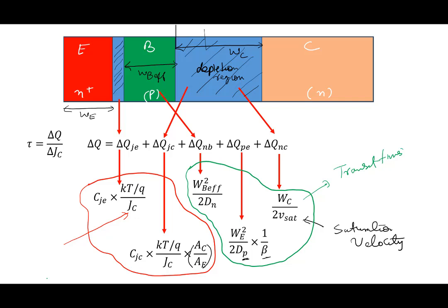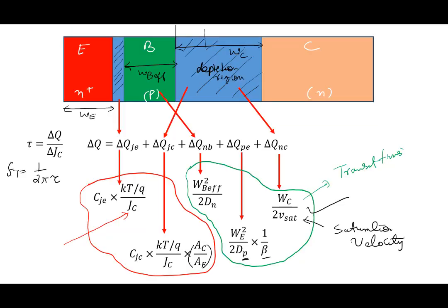we had discussed a little bit the source of this particular delay, the collector transit time. And I also mentioned that if you really try to create a transistor with very high speed, then you will eventually get limited by this particular transit time. So let me also add here that this is related to Ft, which is 1 by 2 pi tau. All right, so that's a summary of what we have done. Let's look at the collector transit time here.